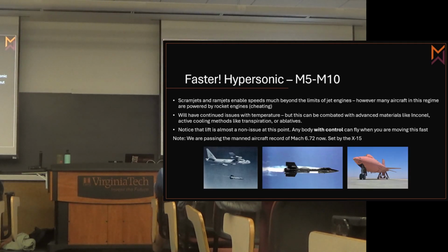Turbojets, very efficient. Ramjets not quite as good, but way better than rockets. Scramjets, no cap. Theoretically, I'd imagine there's a cap mainly on material temperatures as we start exceeding Mach 25. But theoretically, no cap, because I could take Mach 20 air, slow it down to Mach 17, and I'm still going to get a big pressure increase. So it still works.